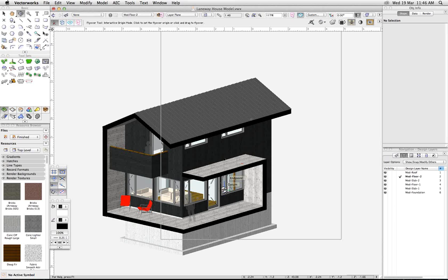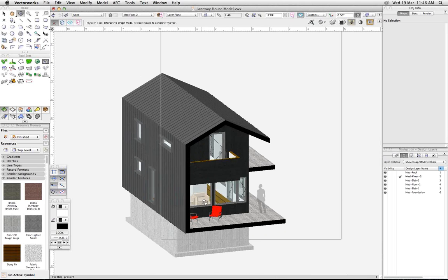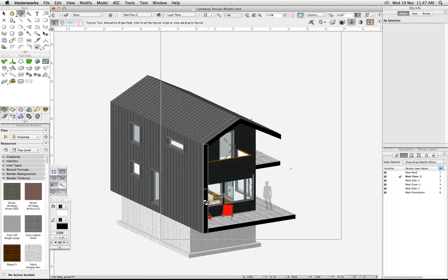You might create the house in a separate file if you have a couple or more people working on the project and you need to split up the work. And in other scenarios, large projects, it may be an absolute necessity that your plans and model are essentially in one file, whereas your site is in another file.